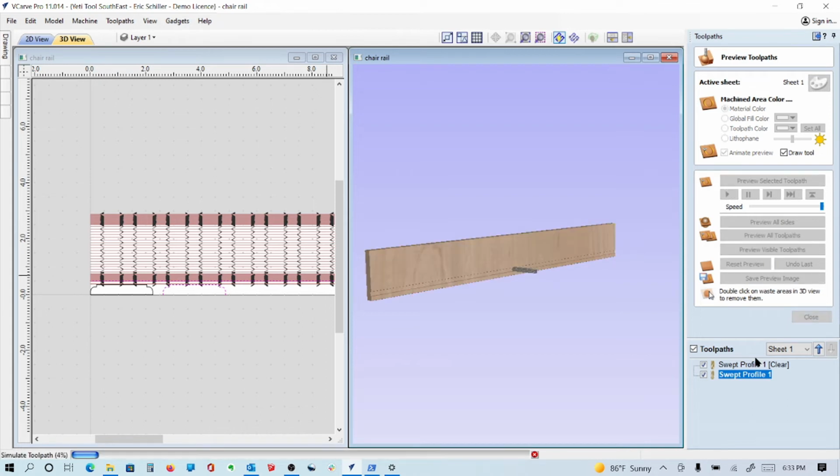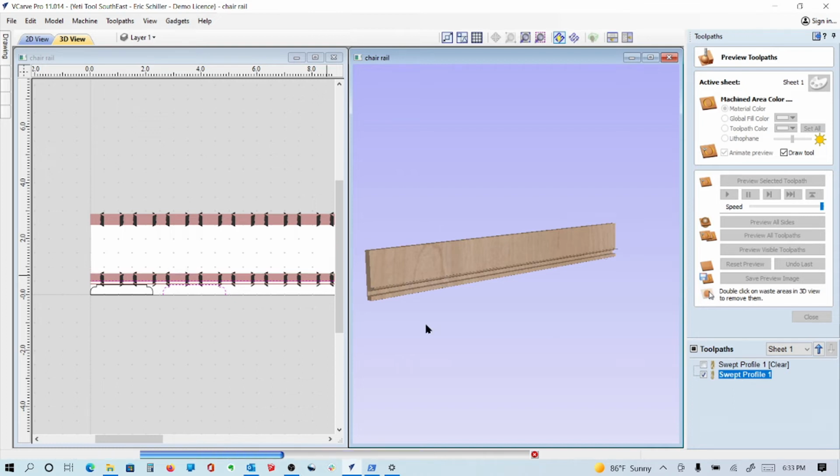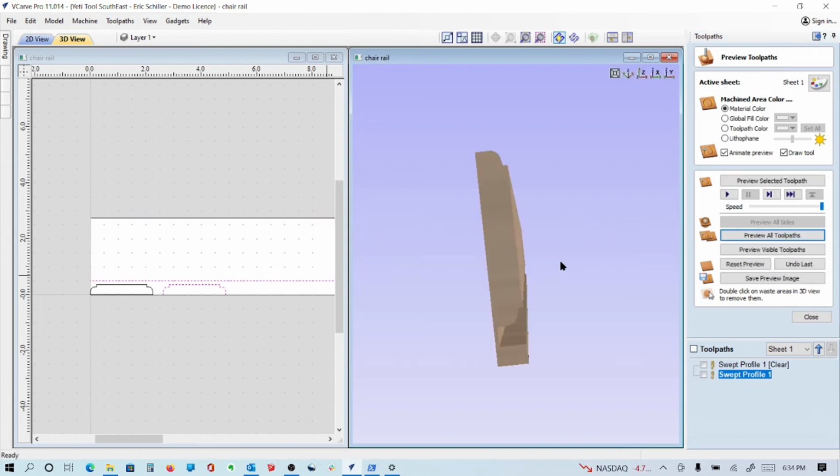So it's going to clean it with a 1/4 inch tool first, where it can, to hog away the most of the material. And we'll go into those settings in a second. And then it's going to come back in with a smaller tapered ball nose, I'm assuming. I just went with what he had sent. I think I may have applied some of my own tooling to it, but it doesn't really matter. And there we have what we wanted. There's the shape that we wanted. So we just have to get rid of that bottom to it and let it apply.